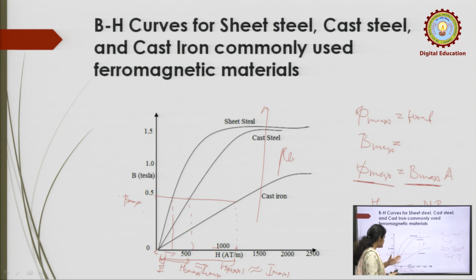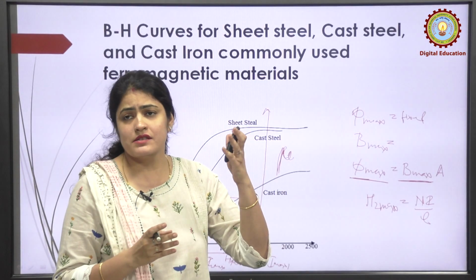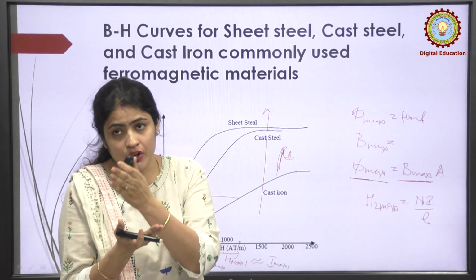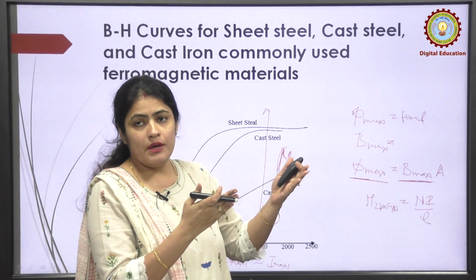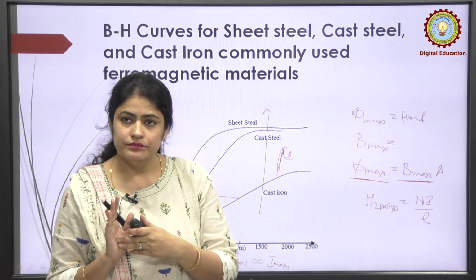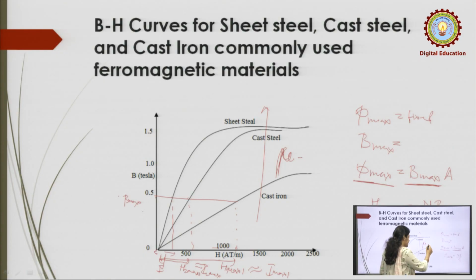Okay. So, as you increase the permeability, suppose you have a very good material whose permeability tends to infinite, then the requirement of current which will produce the total amount of flux is reduced. So, if your permeability tends to infinite, your magnetizing current will tend to 0. Because this magnetizing current concept comes in the transformer, it is very important to understand this.